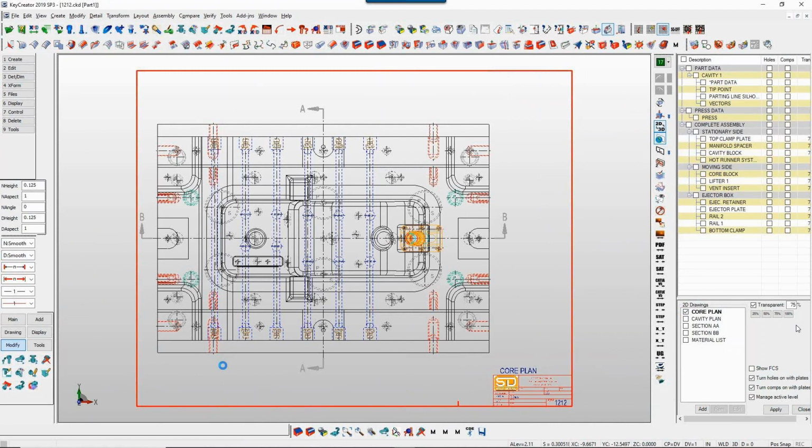So what ends up happening is if the engineering department is super overloaded, they have to skip that phase because they just don't have time for it, and now the shop spends those extra 6 hours anyways. So we need to make it very, very simple, quick, and also with no room for human error, right? If you're manually figuring out ejector pin lengths, the chance of human error, if you have a lot of ejector pins, is pretty high.